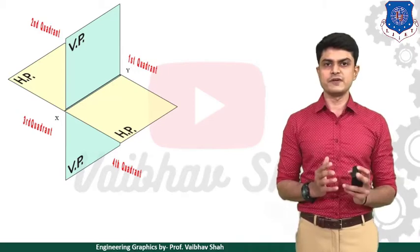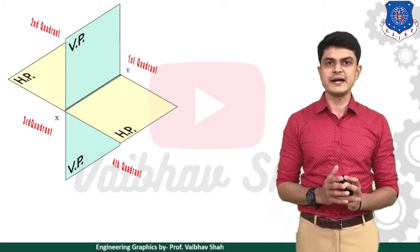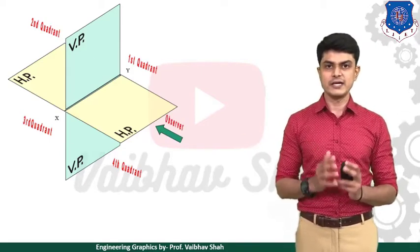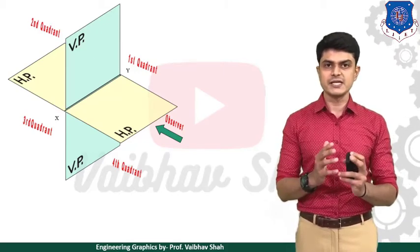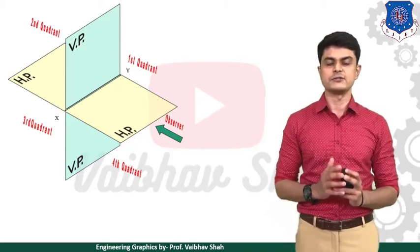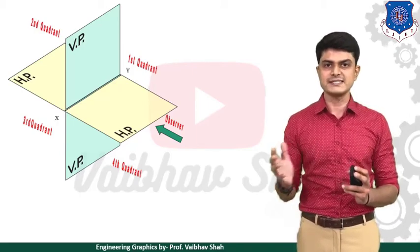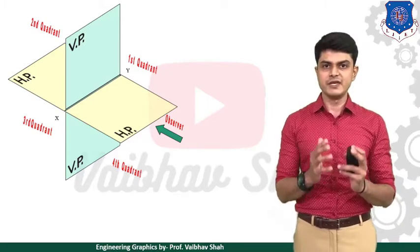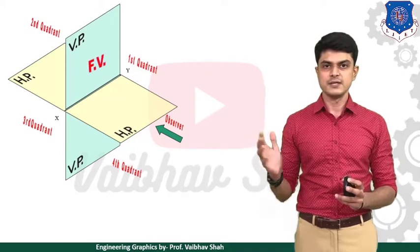Let us suppose we put an object into the first quadrant, and we observe that object from this direction, then we get its front view. Front view means we are observing that object from the front direction. If we are observing the object from this direction and have the front view of the object, then we get this front view on the vertical plane like this.